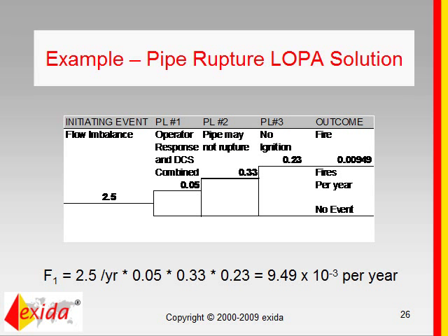And we will see this in just a bit with some example protection layers. But for a basic process control system, the typical probability of failure that you can claim is 0.1, but we'll see that in just a bit. So I hope that gives you some idea of data sources that are currently available.